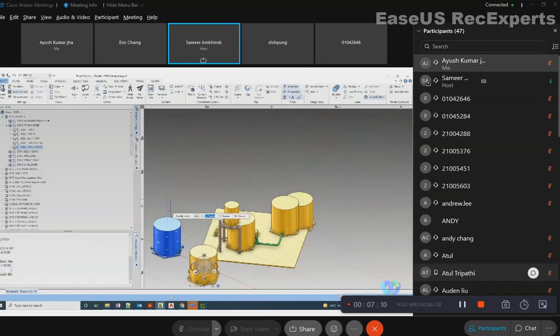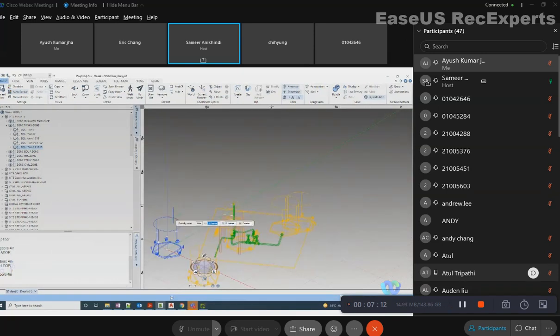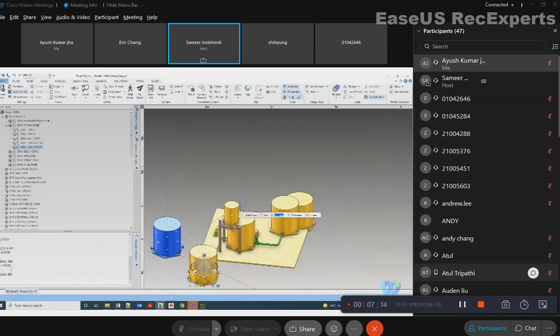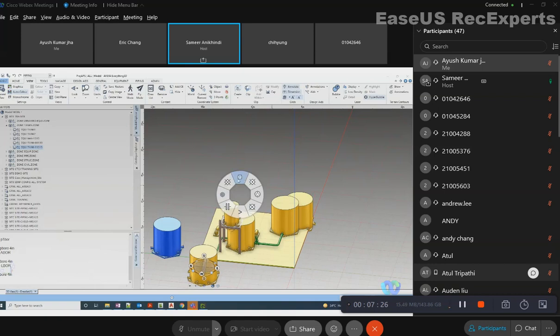You can see the axis down here, right? But if I go back to my world coordinate system, go to view world coordinate system, it is set back to the original point. And now let me measure the top of this tank. So you can see the value is 2.67, 5.1. Earlier it was 4.6, 4.6 something, right? So this is with respect to world origin.